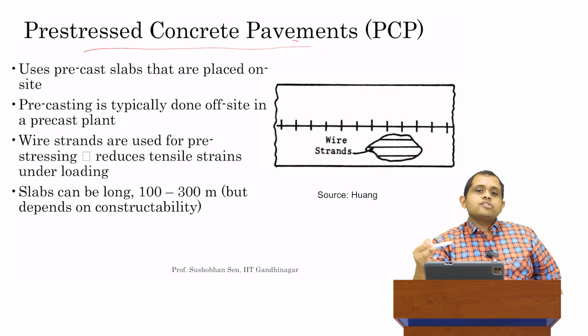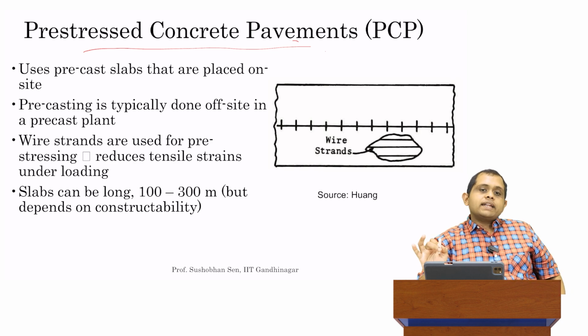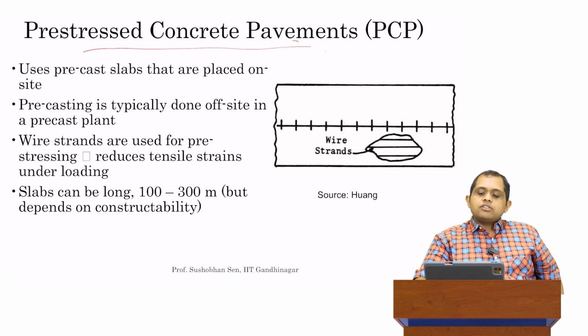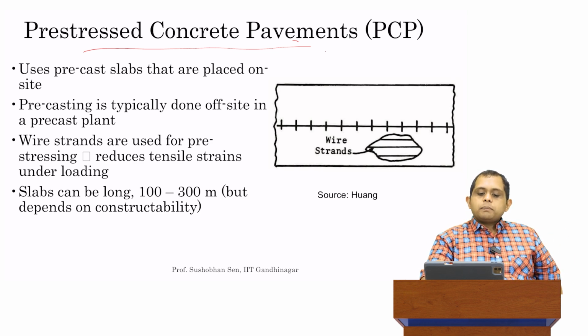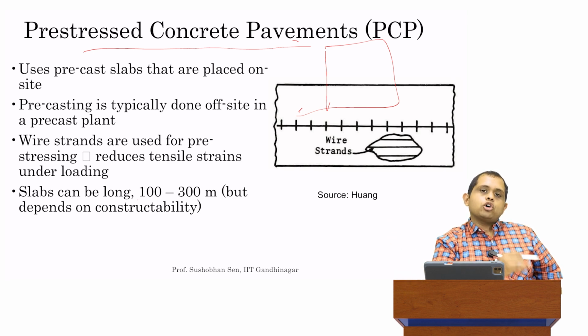And in India, one issue is that many people don't respect barriers and they tend to drive on roads which have not acquired adequate strength. That can lead to some premature cracking, so that is a major disadvantage of using rigid pavements. Precast slabs are a modern technique to overcome that. In this case, you basically have a precasting plant, where you pour the slab in the plant itself, so you are not doing the construction on the site.